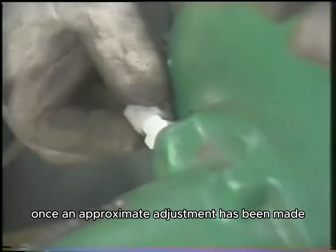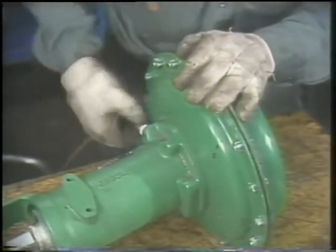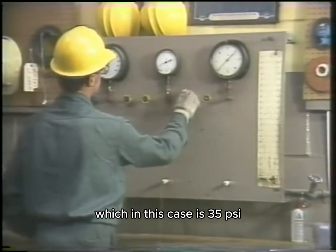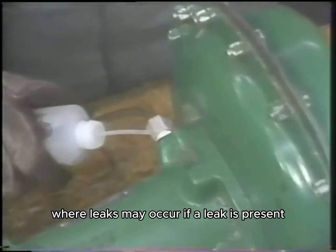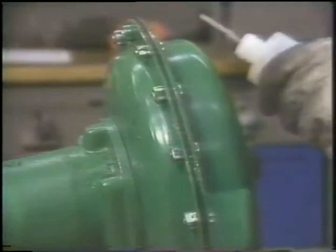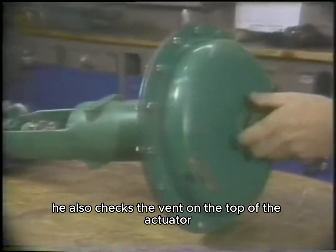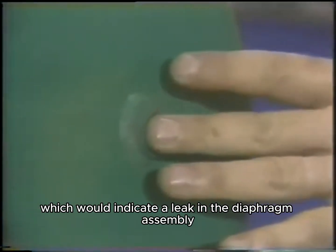Once an approximate adjustment has been made, the actuator is connected to a source of instrument air. Before making any final adjustments, the technician tests for air leaks. To do this, he applies full operating pressure to the actuator, which in this case is 35 psi. Then he squirts a leak detector on areas of the actuator where leaks may occur. If a leak is present, the leak detector will bubble. He also checks the vent on the top of the actuator for leaks. By putting his finger over the vent, he can feel for a buildup of air pressure, which would indicate a leak in the diaphragm assembly.